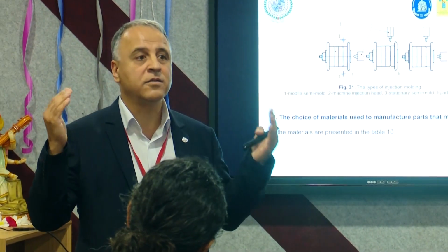Last but not least, the students must make a recommendation and choose the materials for all the elements of the mold. In the case of the active plate of the mold, be careful, we need what? High strength steel. In my lab, the active plates we always make using molybdenum chromium steel. Otherwise, we can destroy it at high temperature, even though we use the cooling system.